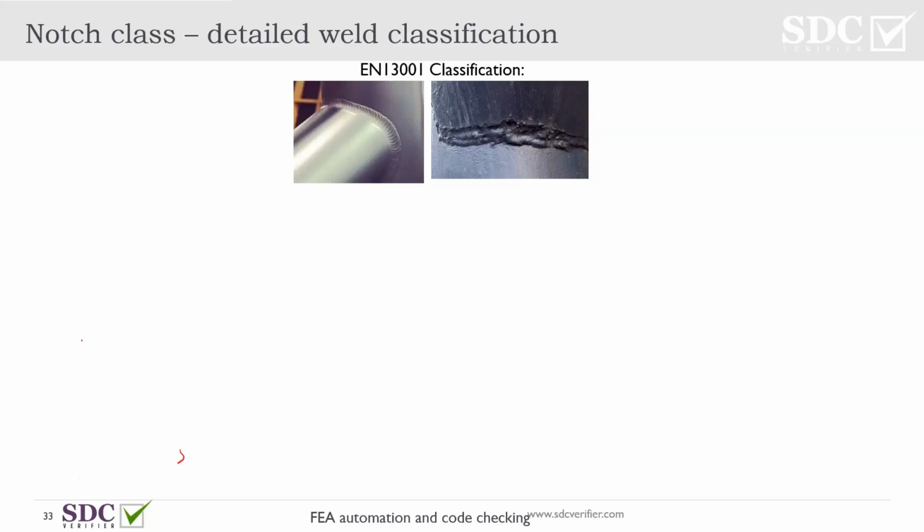When we're talking about the welding quality, which is regulated by the ISO standard, there are different qualities prescribed by EN 13001: quality B*, B, C, and also quality D. Depending on how good your welding quality is, you can extend or reduce your fatigue lifetime, right? The better your quality is, the longer your lifetime is.